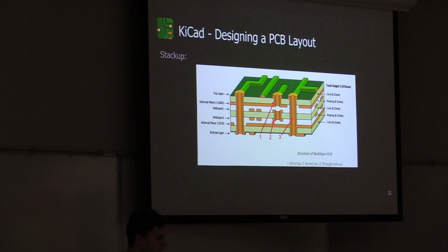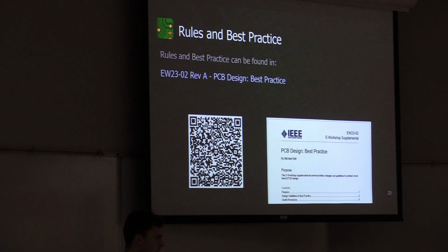Oh, yeah, it's written right there. So going from your surface to a layer just underneath would be called a blind via, and then a buried via is one that's completely buried within the PCB. And then you've got a through-hole via, which is going through the entire board. Just slight definitions. But yeah.